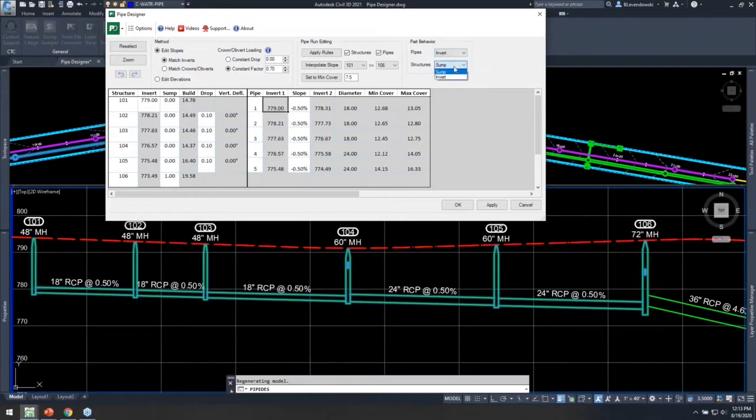With the structures, what am I controlling? Okay, that's what the setting is about. Right here, I'm controlling sump, and the invert automatically gets calculated based on sump values, drop values, and pipe slopes. But if I set this to invert, now sumps are calculated such that if I change the invert value, the sump is calculated over here. There's always undo functions in here. These don't undo things in your drawing, but they will undo table edits within Pipe Designer.